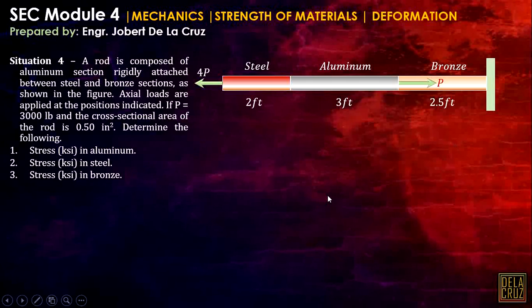In order for us to calculate the stresses, we need first to calculate the forces in each material. So how do we calculate that? We can just cut this portion at any point. We can do that, but I will introduce to you this axial diagram. Actually, we can use the axial diagram so we don't get confused with the forces when we cut. Sometimes the cutting can be confusing.